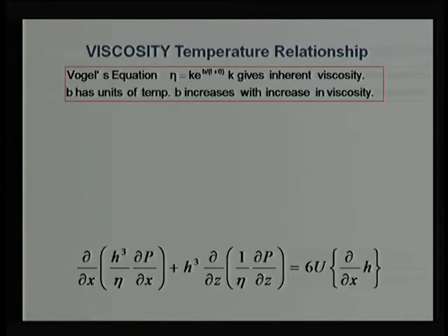Now, this was related to the pressure viscosity relation. We know very well, or we have studied when we were discussing liquid lubricants, that the liquid lubricants are a strong function of temperature. With increase in the temperature, viscosity of liquid lubricant decreases, and we gave 2 relations. We discussed 2 relations there, which are Vogel's relation and the Walther relation.